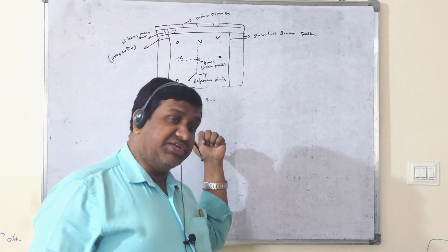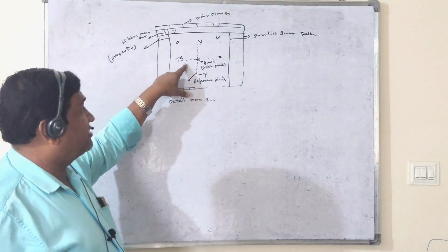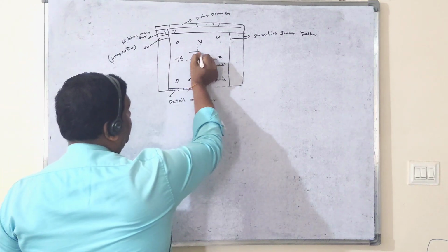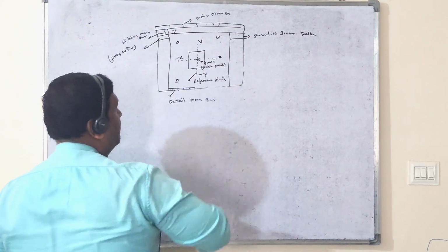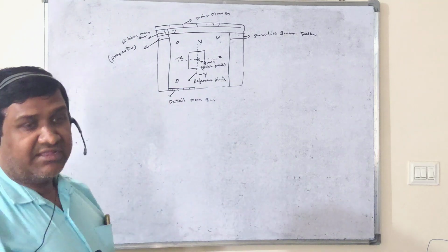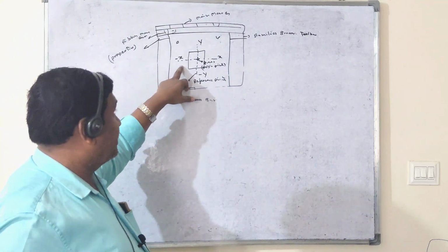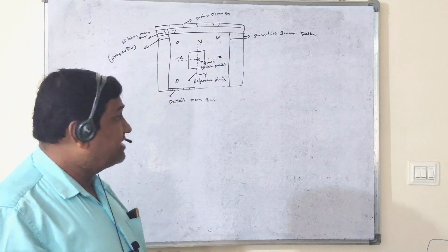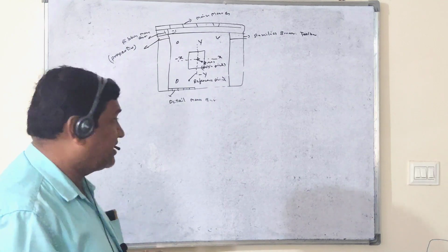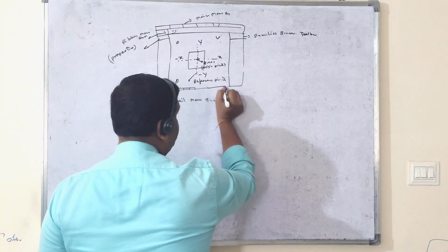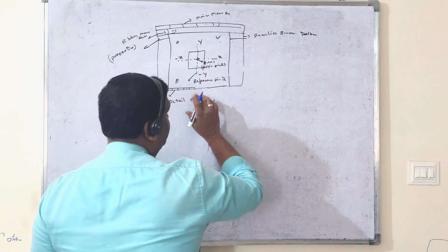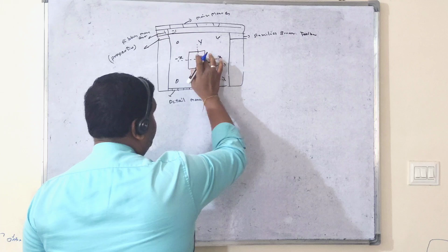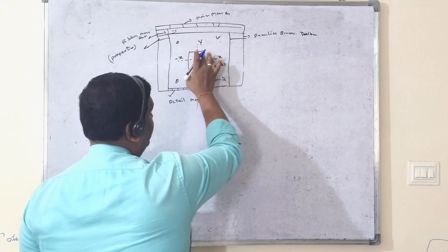In between those symbols we are going to create the project. But here in family creation, with the help of this reference plane, you have to create the families directly here only. Because this view is your family creation view, and based on the reference of this plane, we are going to create the families. So this is the way we create the families while creating a new family category. How it is created practically, I will show you and explain.